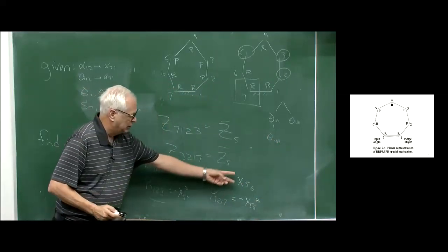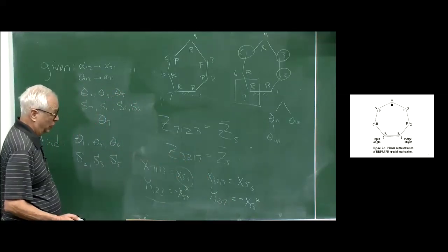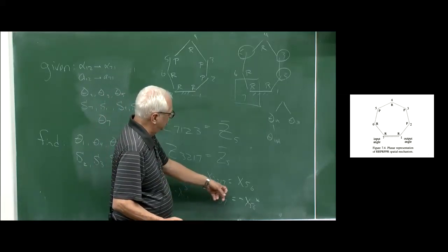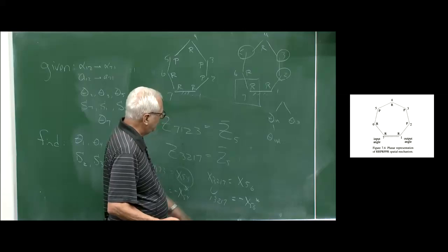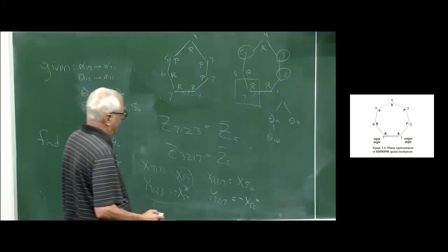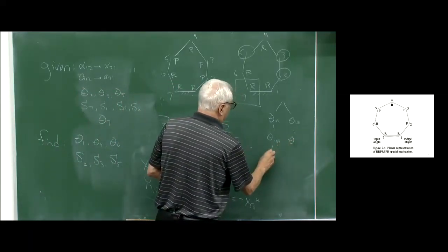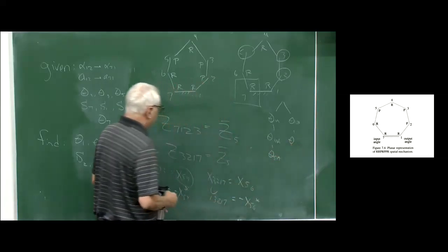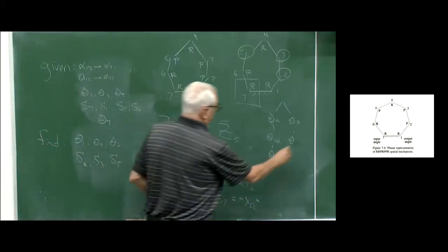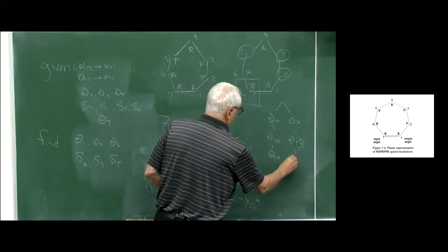And then from these two equations, when we expand them, you're going to get theta 6 pop out. Sine and cosine of theta 6 are the only remaining unknowns, because thetas 3, 2, 7, and 5 are given. And for the A case, theta 1 will turn into a number. A lot of evaluation, but you can get two equations, two unknowns, and the sine and cosine of theta 6. Then we're going to go back to these two equations, put in theta 1b, and get the sine and cosine of theta 4b.